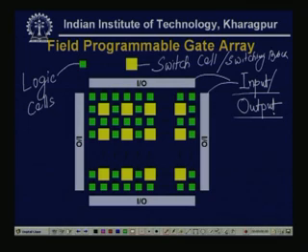Mainly this is fixed hardware, like a form, where three different types of hardware, the logic cells, switching blocks, and the IO blocks are available, all arranged in a 2D fashion, and they are programmed from the outside. So, this is the overall concept of the FPGA. Later again we will discuss in detail.